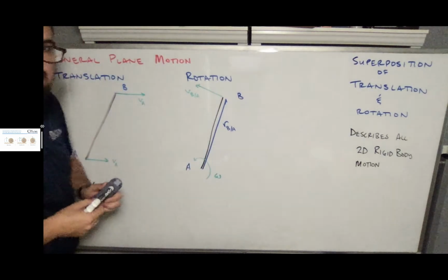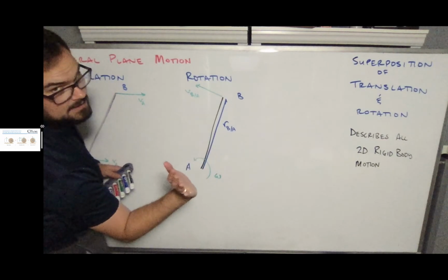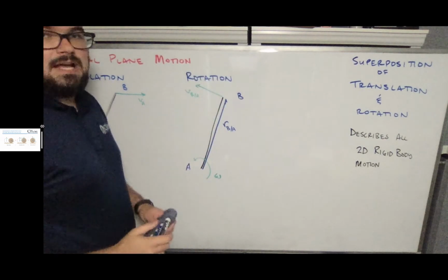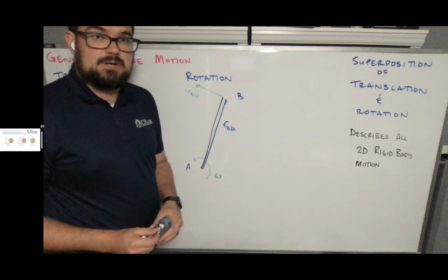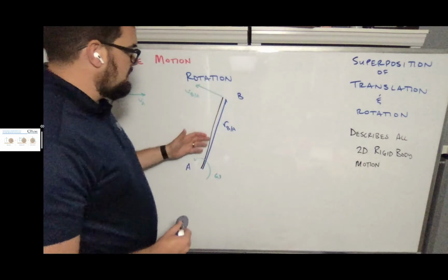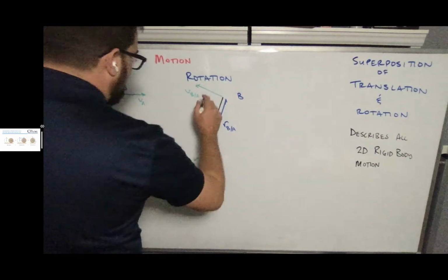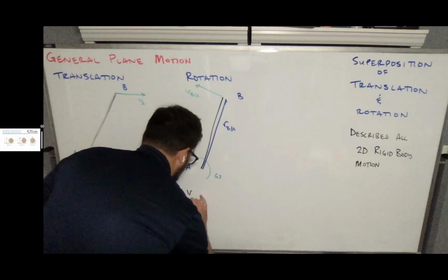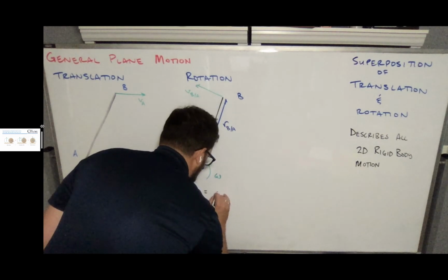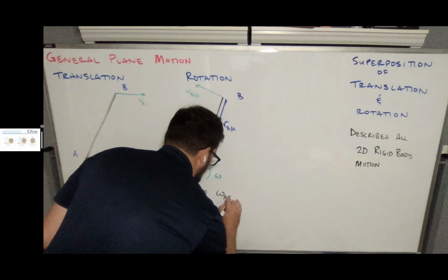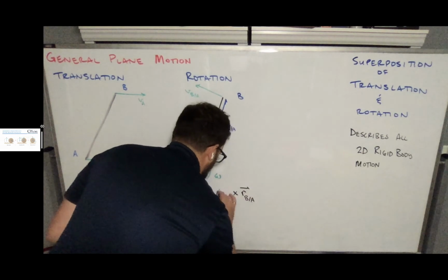Now, I hope this puts you in mind of that relative motion. What we've got is omega, positive direction. So omega cross R gives me the velocity. And if we were looking at point B from A, this rotation is what we would experience. And so now we have this rotation component. Now, we said that we could use superposition. So the idea is that here we can say that the velocity of point B with respect to A is equal to omega AB cross R, B with respect to A, which is what this diagram shows.